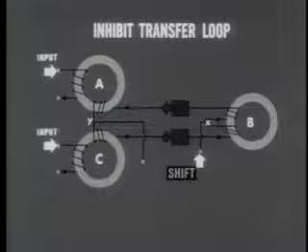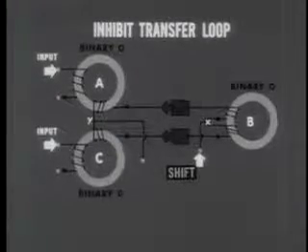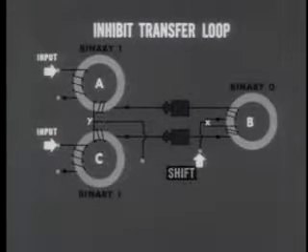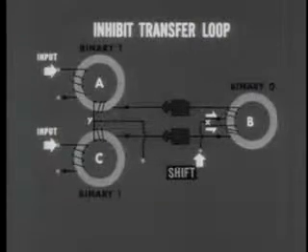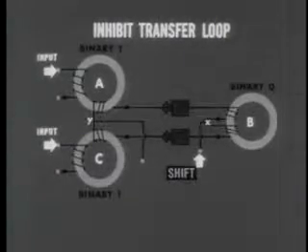All three cores are cleared to 0. A non-dot input is applied to core A, switching it to binary 1. And for our first operation of the loop, core C is also switched to 1. Now the shift pulse is applied. And the question is whether the branch currents into which it divides at point X will be equal or unequal. The answer depends on the impedances they encounter.